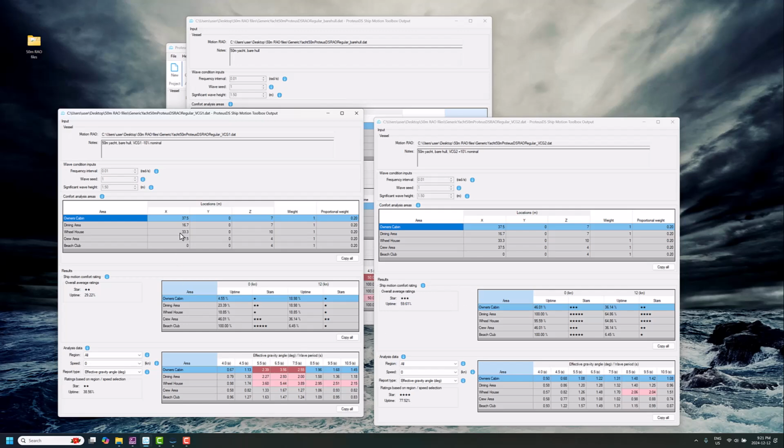So I really wanted to highlight what that workflow looks like and how to be careful when you go through calculating the motion RAO values with the ShipMo3D toolset, and then make it easy to jump back and load those motion RAO files for making lots of comparisons.